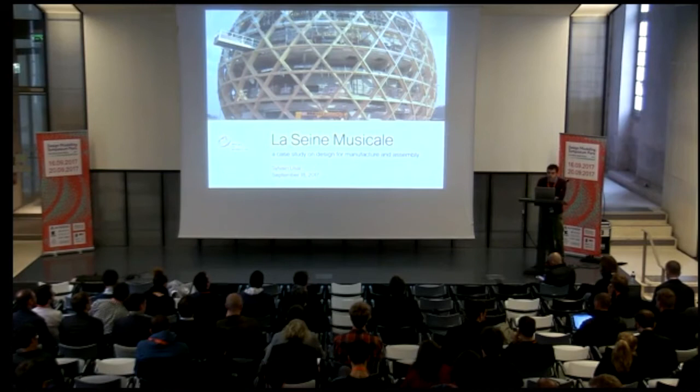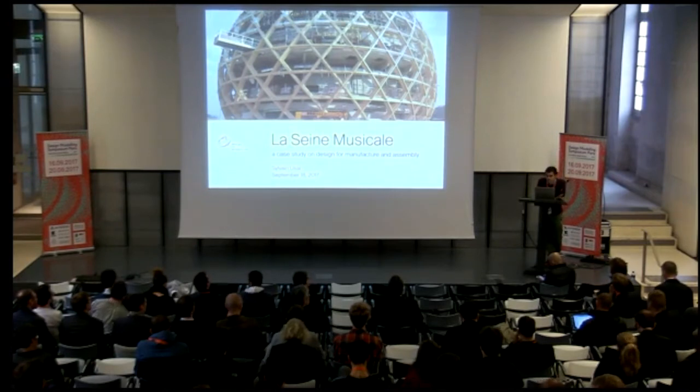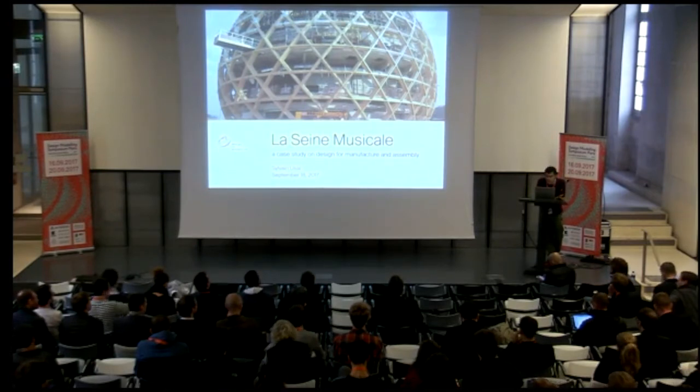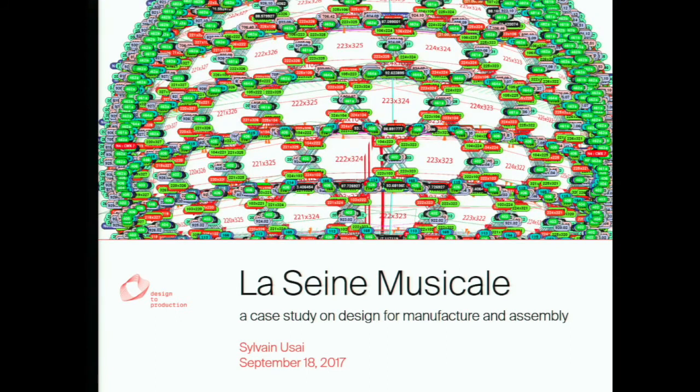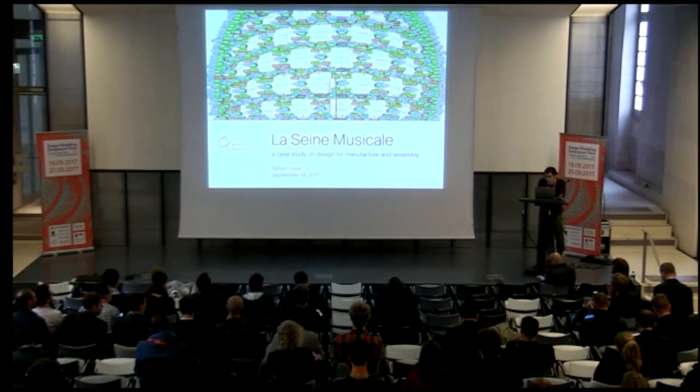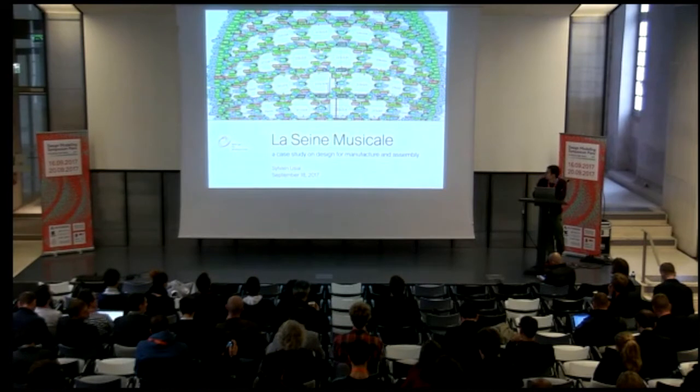So the paper we submitted with my colleagues Arno Stelling and Fabian Schur is called La Scène Musicale, a case study on design for manufacture and assembly. And the goal there was to explore the solutions specifically developed for this project and the way workshop, pre-assembly, and on-site constraints have been integrated in the parametric modeling process of this complex timber structure.